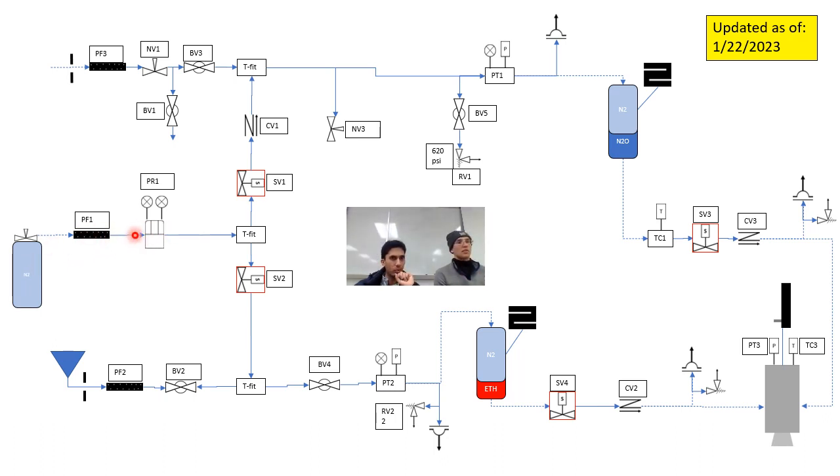So it just holds it there. Which one needs to do? RPL1. It just holds it between PR1 and the actual N2 tank. So it's initially set at 0 psig, right? Yes. Okay. That's at atmosphere. And what it's doing is really locking down this section. So I'm going to start controlling it as well. Both of us can control it.